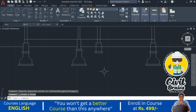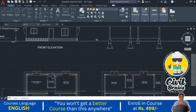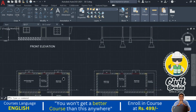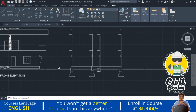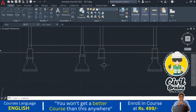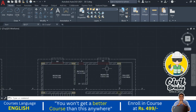Only the PCC of this wall trench, and above that the wall trench, above that the PCC, and the plinth beam over here. So this is a main wall, that's why we are providing the plinth beam over here. Okay, so this is how we have done it in the actual project. So next, for the stability of the wall, we need to provide this foundation. That depends on the project. Not in every project do we need to provide that, but it is on the safer side, so we provide it. Depending upon the loads also it will be done.